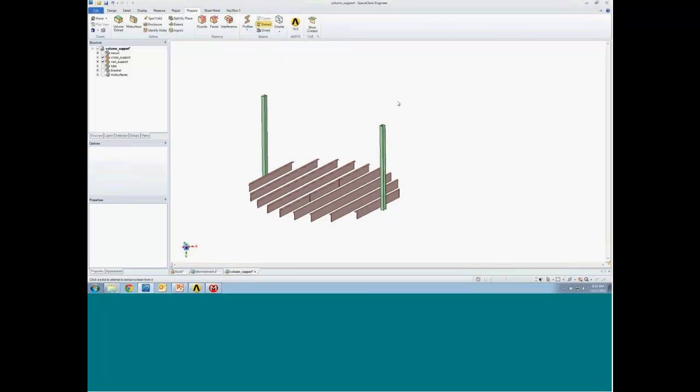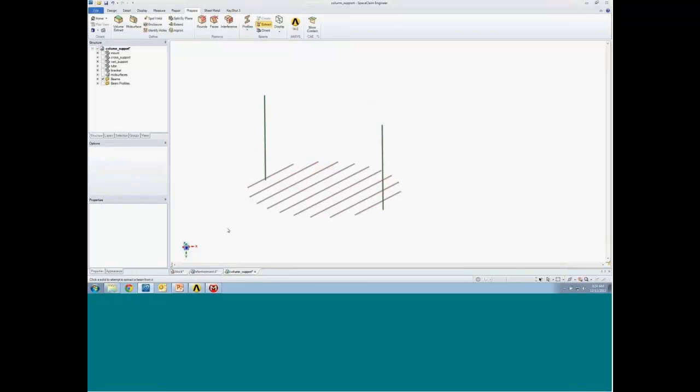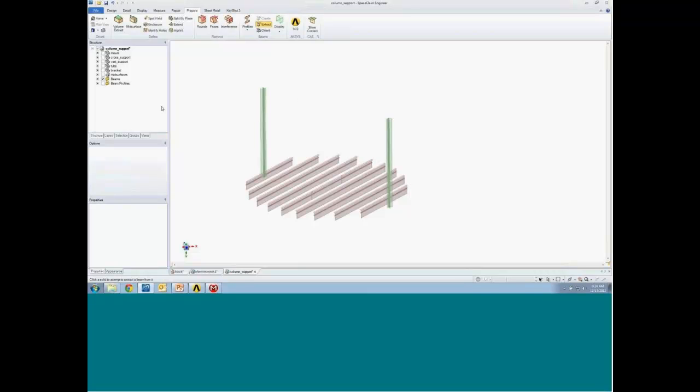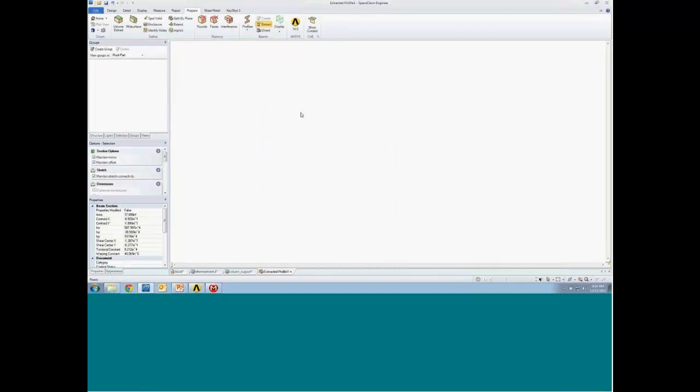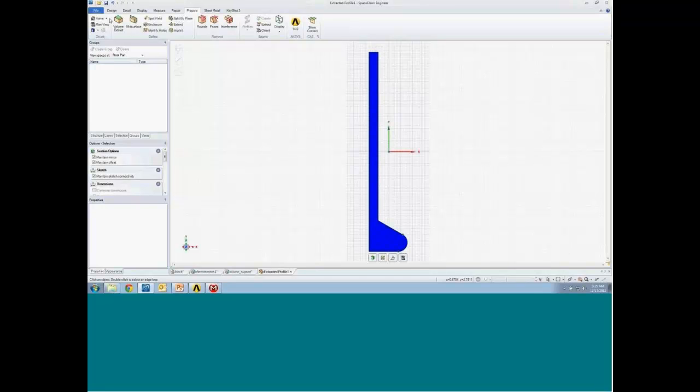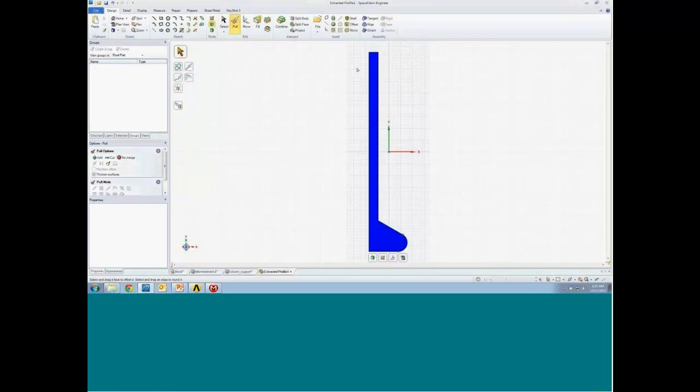Well, we have a tool for that too, extract. A similar workflow, same kind of thing. Grab everything that's a beam element, and we'll turn it into a beam right away. Now, what we do to simplify things is show you just the wireframe, but you can always go back and show sort of a silhouette of what that cross-section actually is. And what we've done in the structure tree is show you all the extracted beams. Now, if you want to go through and look at the cross-section of any of these, sure, you can do that very easily and even modify it.